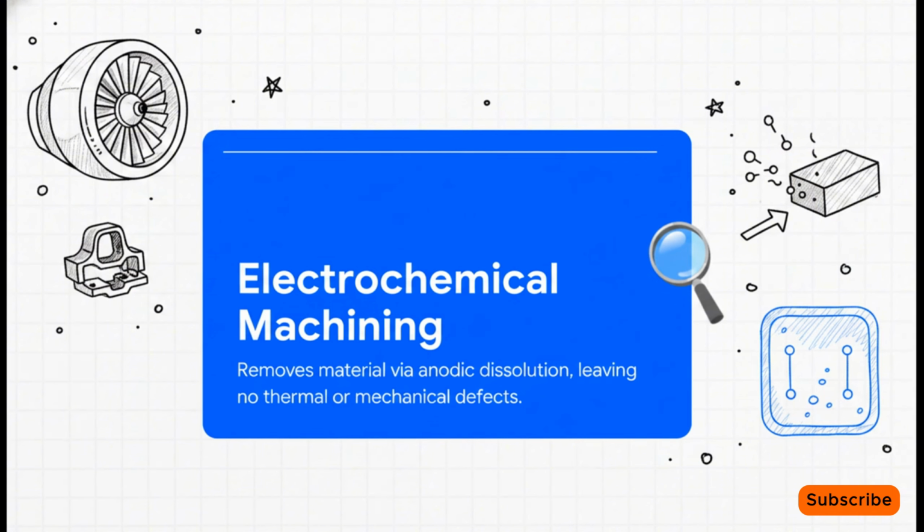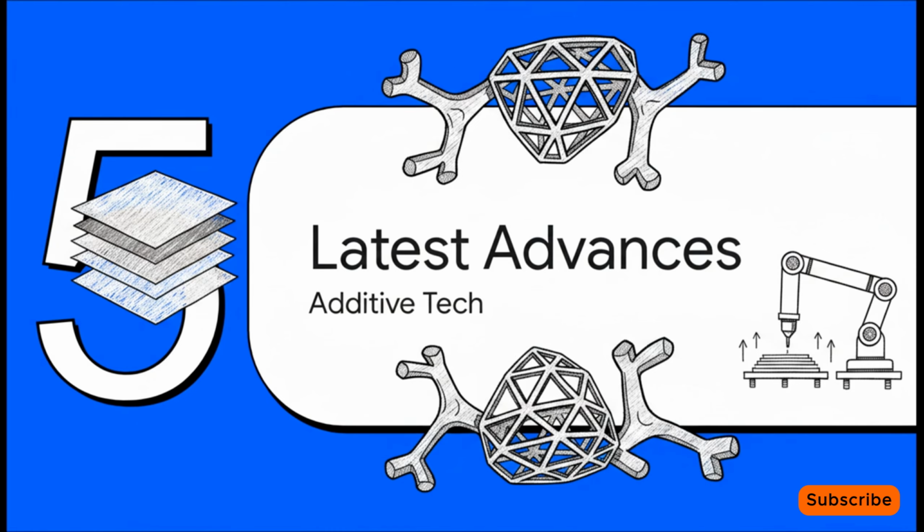Well, electrochemical machining, or ECM, is your answer. It uses a highly controlled chemical reaction and an electrical current to essentially dissolve the metal away at the atomic level. It completely avoids those thermal and mechanical defects, making it the absolute perfect choice for creating highly complex, contoured geometries inside super tough, heat-resistant alloys. And that brings us to our final stop, Section 5, the latest advances in additive tech.